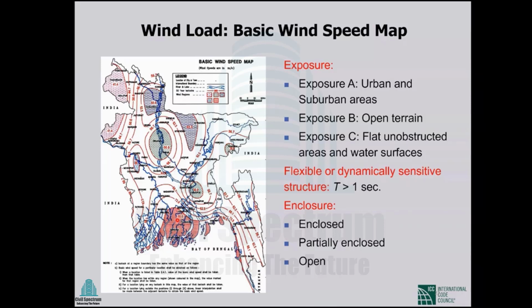Even with the latest data, the actual speed that we can derive to calculate wind load is not that conservative. So we became conservative and we followed the previous version of the code. So the contours and everything are similar.